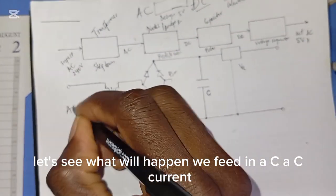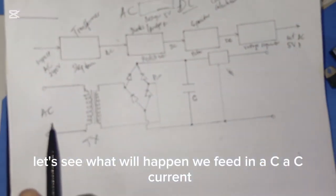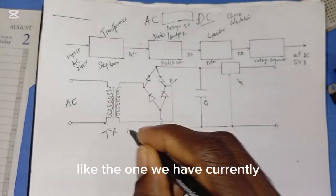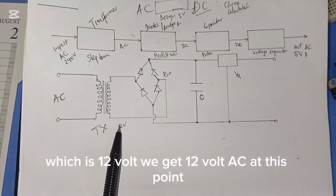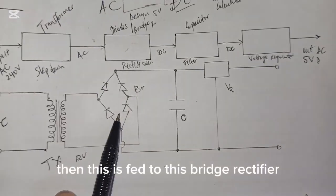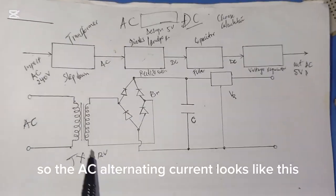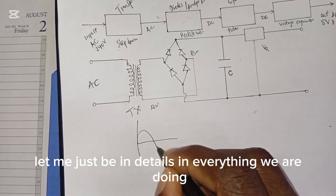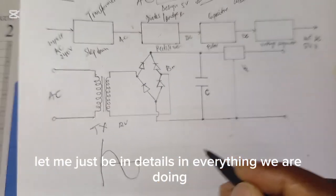We feed in AC current. It steps down this voltage to a manageable voltage, like the one we have currently, which is 12 volt. We get 12 volt AC at this point. Then this is fed to this bridge rectifier. So the AC, alternating current, looks like this. Let me just be detailed in everything we are doing.